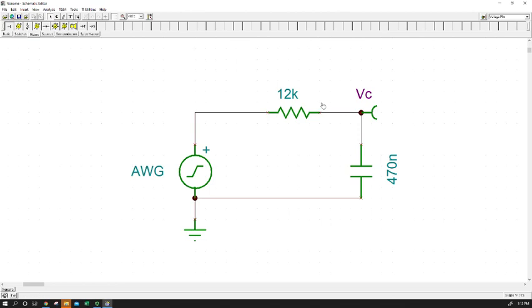Now, one trick when we look at those other components is we can choose values for our deliberately selected components that are much bigger than the range of probable error. We know that any kind of long coaxial cable, such as our scope leads, is going to have a little inherent capacitance. And in fact, we have a setting on our scope leads that can help account for that. But another way to account for it is to make sure the capacitance on our circuit is significantly greater than whatever is in our scope lead. So the deliberately chosen values, the things we know more, are going to outweigh the measurement error that we're never really going to know. And that's one trick to make our measurements easier and more accurate, more representative of the true values.